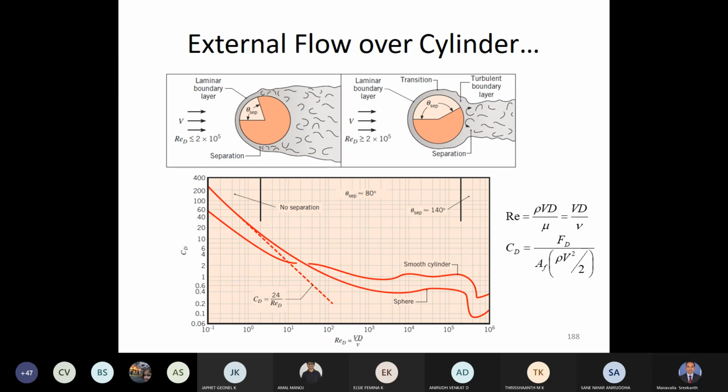Okay. You also know that the golf ball has got dimples on its surface. Those dimples are deliberately kept so that they will disturb the laminar region. If the laminar region is disturbed, the flow becomes turbulent, and when the flow is turbulent, the flow separation is delayed, and therefore you will get a larger range of move of the golf ball. So that's the reason for that.